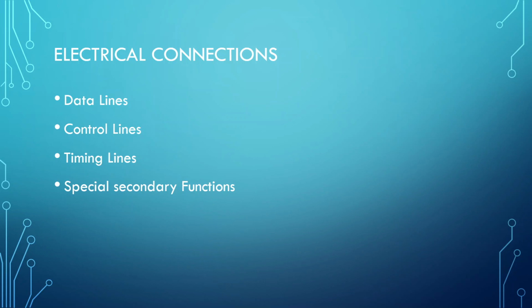Our 4 most commonly used control lines are RTS, which is request to send. So device A would say, hey, I have something I want to tell you, and it would bring that line high. And then the other device would say, CTS, clear to send, go ahead and tell me. And then we also have data set ready, which is either DSR or DCE, depending on which protocol you're following. And then you also have DTR, which is your data terminal ready, or DTE. So again, two different options there, which drives me freaking batty.